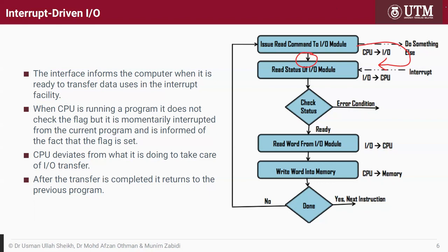The processor can sleep and save power, and when the device is ready, it can give an interrupt and wake up the processor. So interrupt-driven I/O is also usable to save power, not just to do multitasking or save processor cycles, but you can turn off power when there's no input-output taking place.